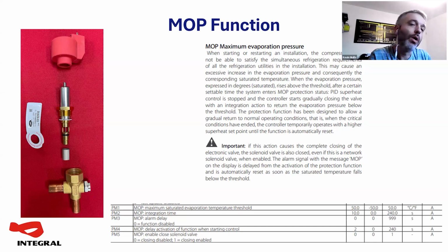So what they've done on all these electronic controllers is replicate that. They're all sensing the suction pressure. So they've got a function that says, if the suction pressure is above this point, don't open the valve anymore.